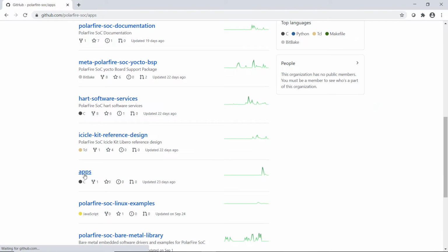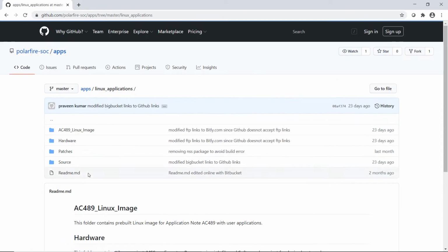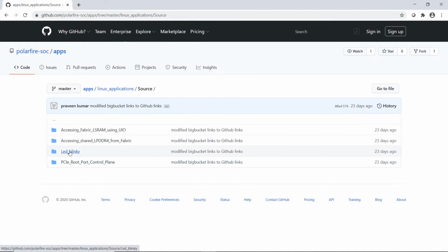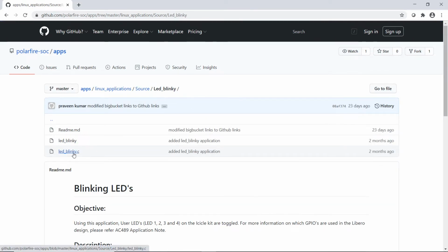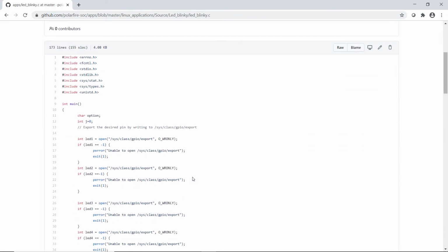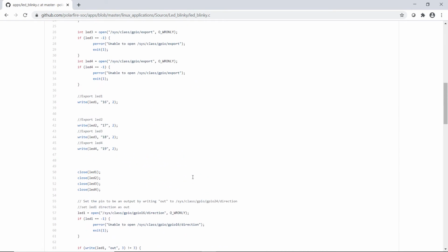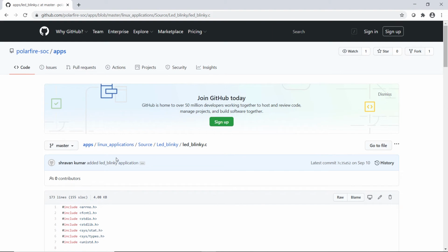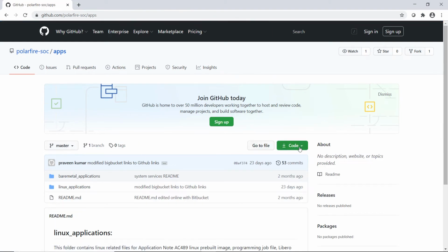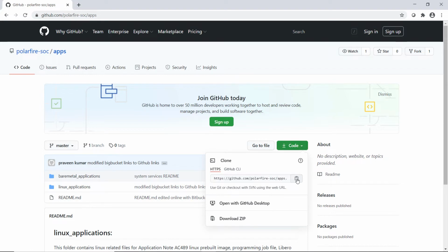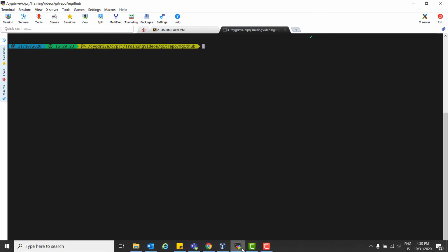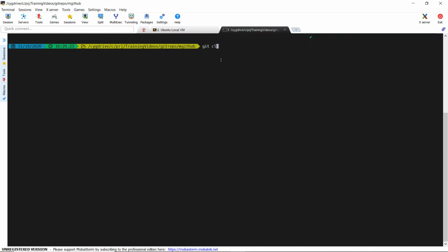The same procedure can be applied programmatically with an application, as the one you can find in the apps repository on the MCHP GitHub webpage. Within the apps repository in the Linux_examples folder, you can find the Linux image with GPIO sysfs file system enabled, an LED_blinky.c application, and its precompiled binary. Let's clone the repository and recompile the source code directly onto the board. This source is already available in the image in the apps repo. We are using it just as an example.